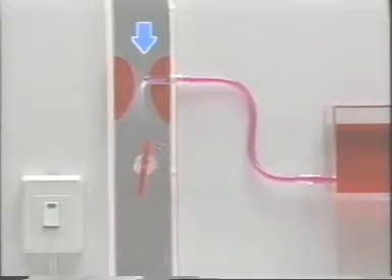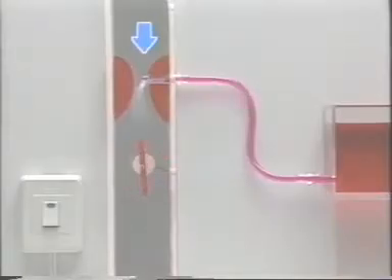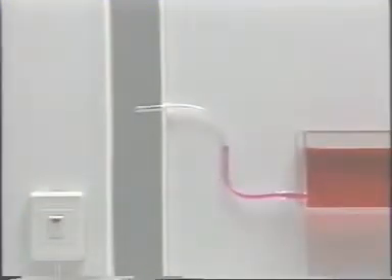This is a model used to demonstrate the principle behind the carburetor. Air is blown in at the bottom, creating a vacuum which forces the liquid out. We will explain the functions of the carburetor using this model. First, we will conduct a test in which the nozzle of the fuel pipe alone protrudes into the air tube. If a vacuum is applied to the bottom of the tube, we can see that the fuel rises in the pipe a little, but due to insufficient air pressure, enough fuel will not exit the pipe.